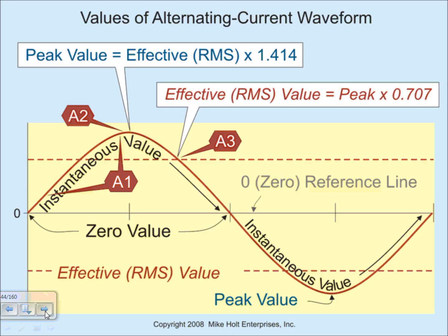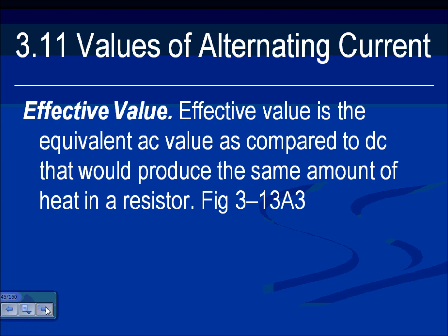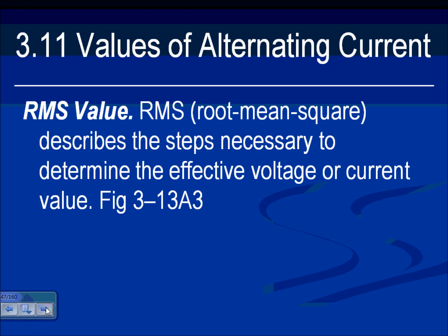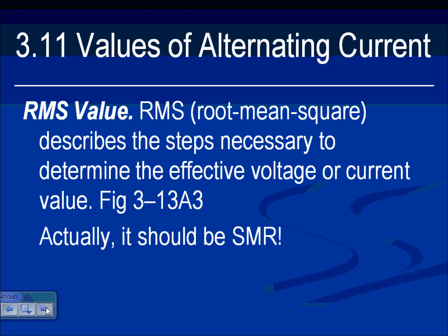Peak value, let's talk about the peak. The only time you're going to be using the peak later on, Phil, my friend, is when we do short circuit analysis. I want to remind you of that value later on. It could affect how your equipment, circuit breaker, will react to the peak of the circuit in short circuit. Other than that, 99% of the time you're using the RMS value, the effective value, with all the calculations and so forth.